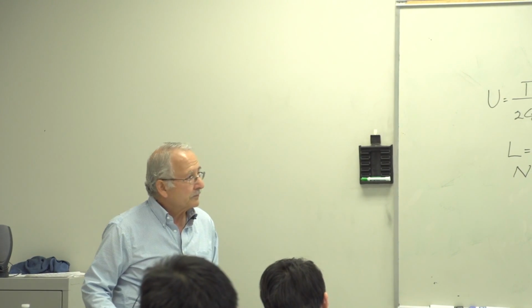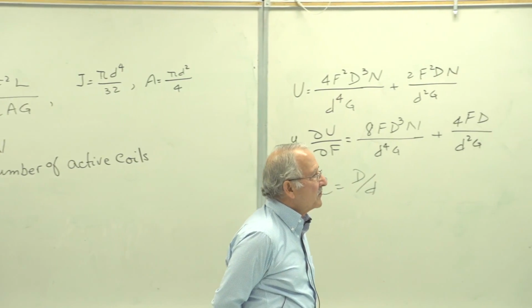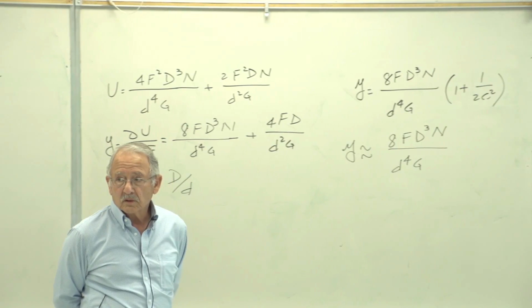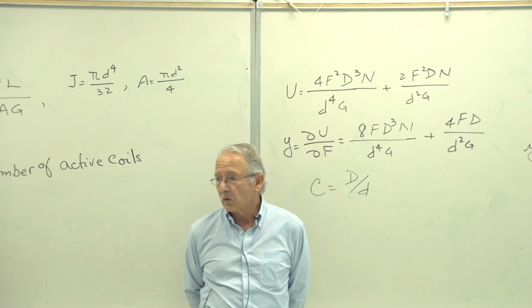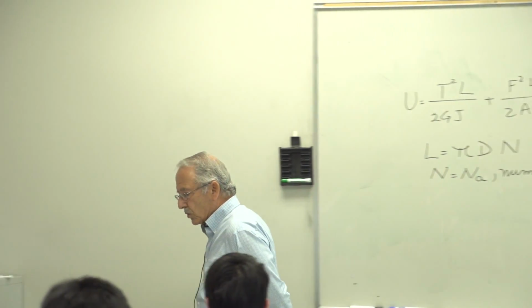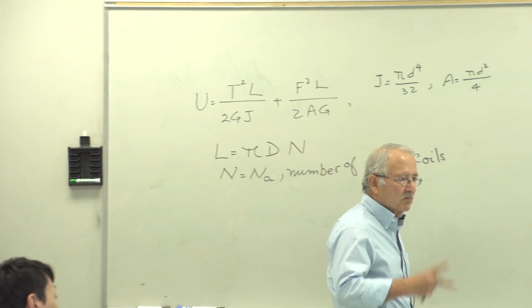Now, remember I was just talking about N, calling it Na, number of active coils and all of that. I'll bring you some spring samples next time to take a look at. But springs can be cut, after they're wound, and treated in different ways. One way is once you wind the spring around the mandrel, just cut it like that. Nothing else. Simple cut.